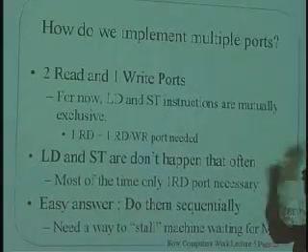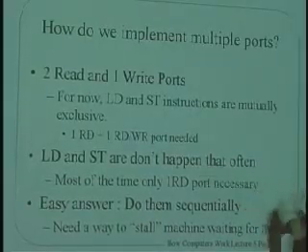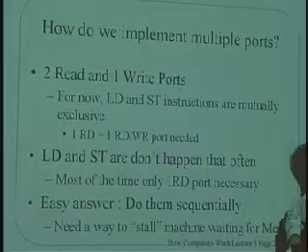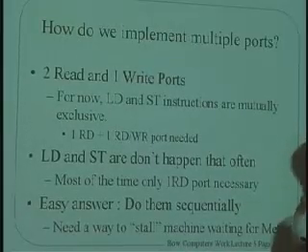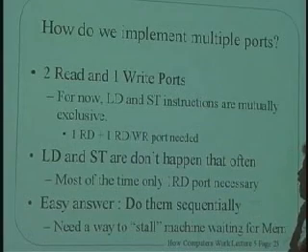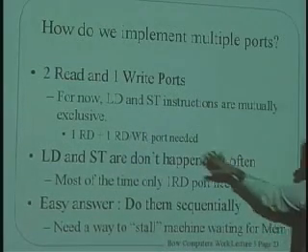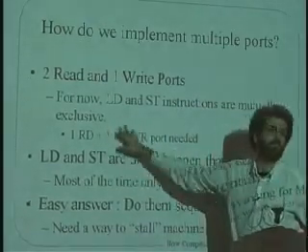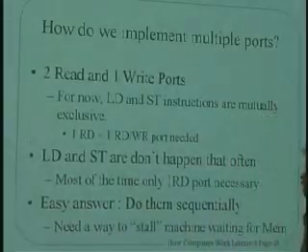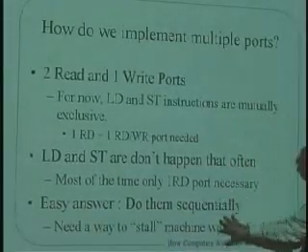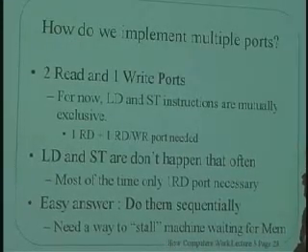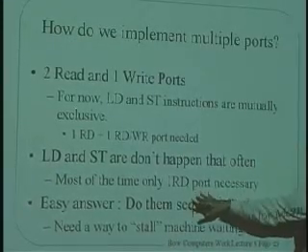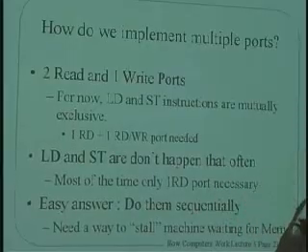Furthermore, we notice that load and store don't really happen that often. The whole idea of our machine is that we're going to do most of our work with the register file, and only once in a while we're going to do load and store. So most of the time we don't even need this second read-write port into the system. And so what we're going to do for now, and we'll talk about how to perhaps improve the system afterwards, is we're only going to use one port. We're only going to use a one-port memory.